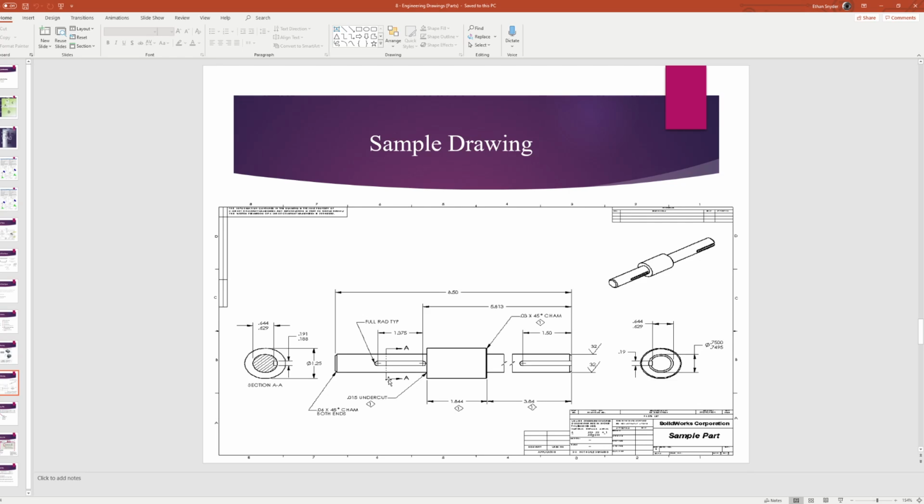It gives us section views when it is necessary, and it specifically shows us where they are. Yes, so it does tell us where certain section views are located. Section AA is around just to the middle left of the page, where you have those two arrow bars with an AA. It's giving us a lot of information with regard to chamfers, what those degrees are, any sort of cutouts, all of that information.